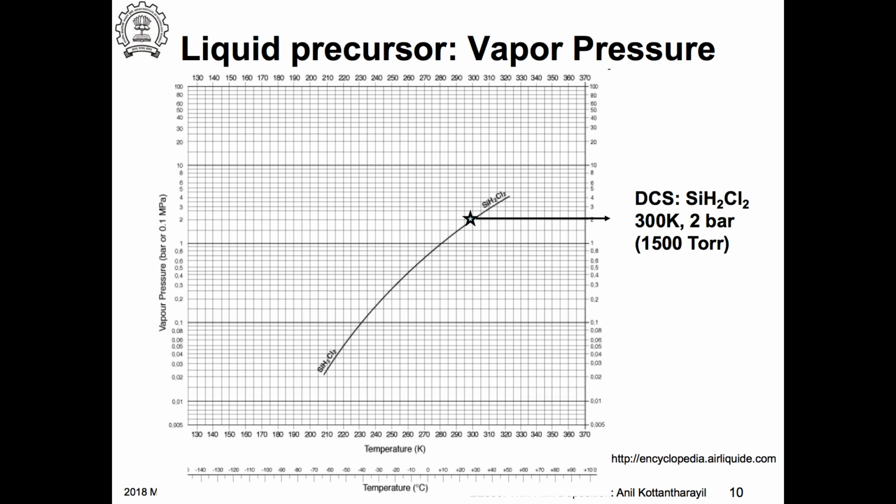We are doing here a phosphorus oxychloride bubbler arrangement, something similar to what you have seen, for phosphorus doping of silicon for making PN junctions, for making solar cells. You have seen the solar cells that we make, right? I showed you the solar cells in one of the previous introductory lectures. We use phosphorus oxychloride, which is a liquid at room temperature, and you bubble nitrogen through this.